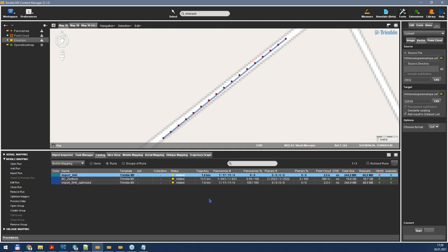The first thing that we can notice here is the difference between the photo positions and the available images in our original folder. So to fix this problem, we have two options. Either we add the missing images, or in the worst case, we need to delete the photo positions for which we don't have images.